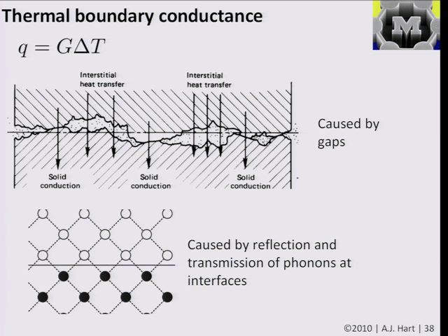And in the macroscopic sense, when you take two things and push them together, like a heat sink on a CPU chip, or a radiator on your car, there are some gaps, some large-scale spaces. And you might want to fill those gaps with a thermal grease or something, but most of the resistance is caused by these gaps. But when you go down to the nanoscale, if you're making chips, for example, you can create atomically perfect interfaces, or almost so. So when you deposit a metal on a semiconductor or a glass, you get an interface that's really like this.